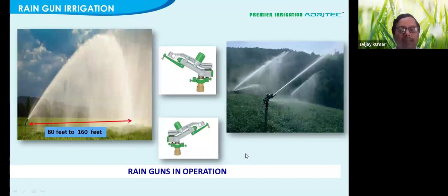Accordingly, you can typically go 6 to 8 hours. If more labor is available and they want to have it for a longer period, it can be done. If you want to go for higher hours, it would be good to automate the system. You can even go for automation, whereby the solenoid valves will take care of the irrigation and the irrigation will happen in the desired fashion.